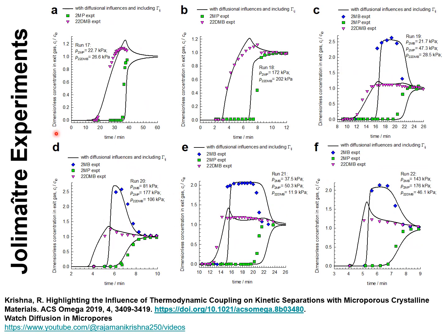To model the breakthrough experiments published by Joly-Maitre, we need to take proper account of both adsorption and diffusion. And for modeling of diffusion inside the micropores, there is a need to incorporate the Maxwell Stefan diffusional formulation, in which due account is taken of thermodynamic coupling effects.